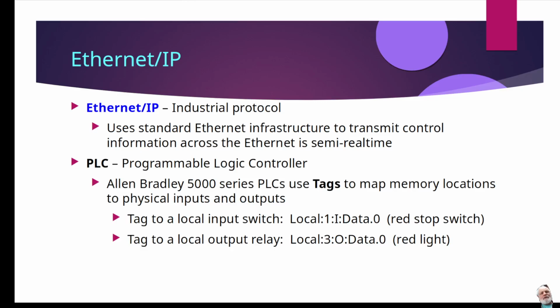The reason they do it all the way up there at the application layer is because Ethernet, when it was originally designed, was designed specifically to be not real time. So it's a bit of a hindrance to Ethernet/IP, because they're sending this clock signal at this high level, since technically Ethernet is the hardware level, and at the hardware level there's no guarantee of real-time communications. So they guarantee the real-time communication through the application layer, and that's why it says here on the slide semi-real time.